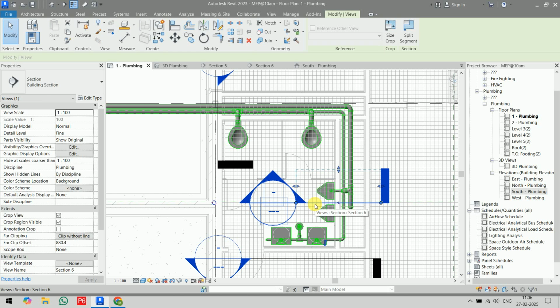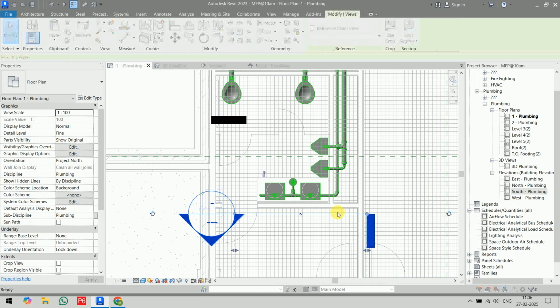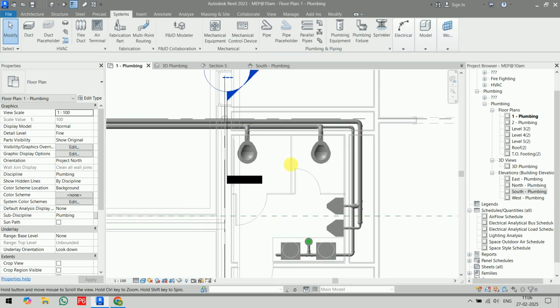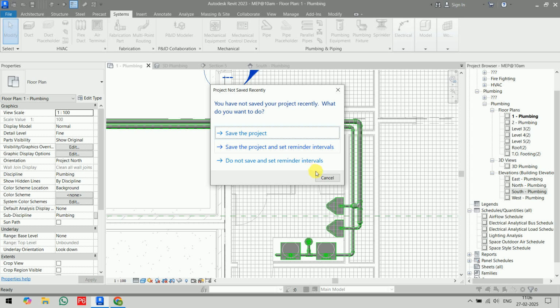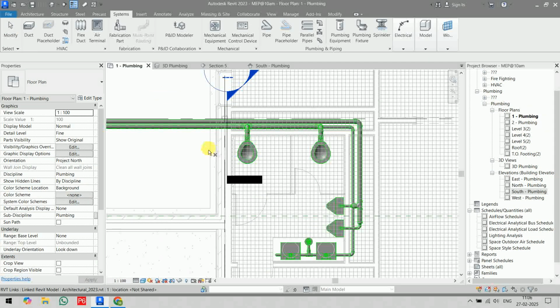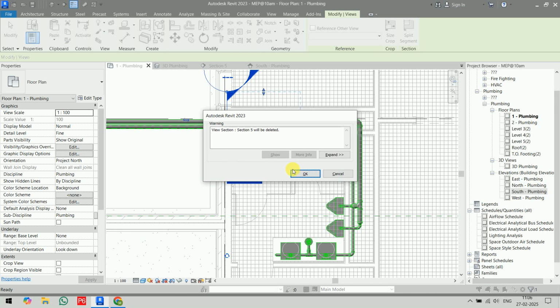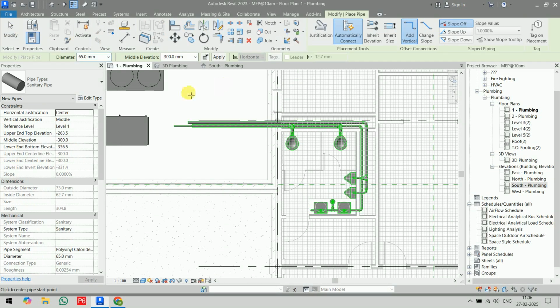Second one is we want to create a cold water system or hot water system for the domestic purpose. We can say cold water supply, hot water supply for the project you require. So what you can do, go to pipe again, and for the hot water and cold water supply also we are using the PVC pipes currently.